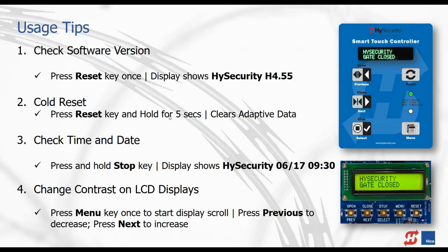This even clears out more data than a power off and on will do, okay? So that's a good thing to know. Check date and time. If you press and hold that stop key, if you watch the display, it'll say HySecurity, and it'll give you the date and time. This is kind of an interesting one.